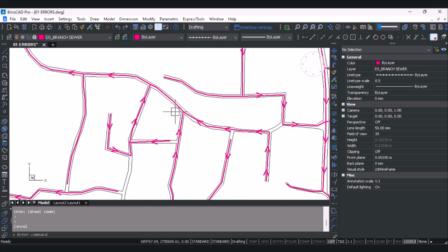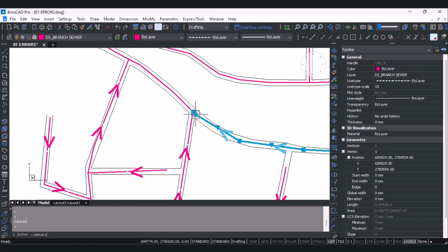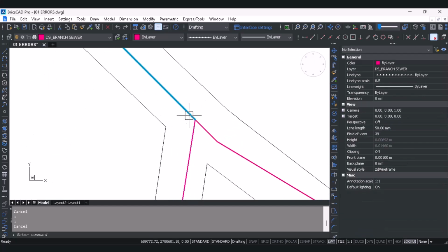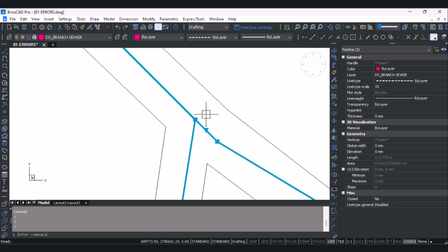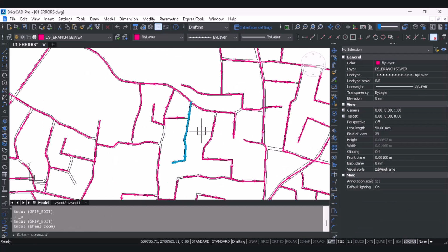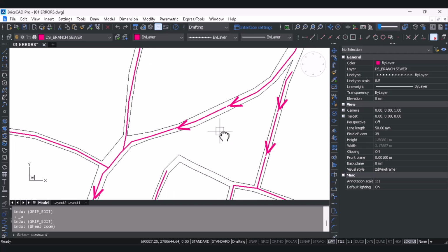But before taking them, we have to ensure that whenever two or more pipes meet at a junction, the pipeline should be broken and the branch pipe should also be at the same point. In this junction, three polylines are meeting and all three polylines should share the same point. There should not be any polyline protruding outwards or remaining away from the junction. These kinds of drafting mistakes should not be there. However, it is not possible manually for any draftsman to be 100% accurate. So we have built a LISP program wherein we can not only identify these drafting mistakes, but we can also correct them.